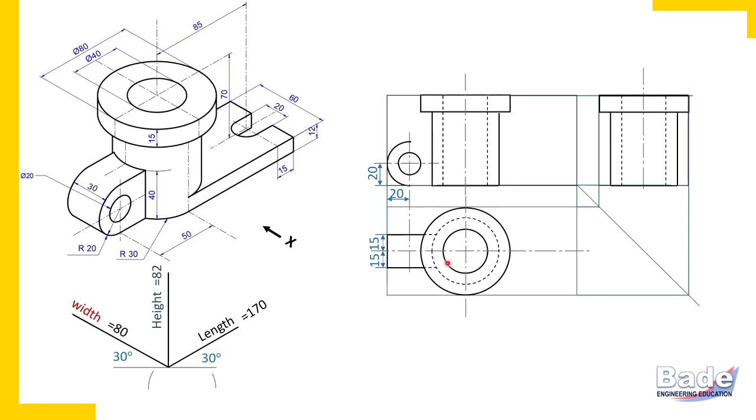Okay. Now check exactly where this U-shaped block gets connected or comes in contact with the cylindrical surface. Watch that sharp corner here, and a corner represents an edge in the opposite side view. So from this corner, check here the horizontal dotted line and the circular dotted line where they meet, that corner, draw the projector.